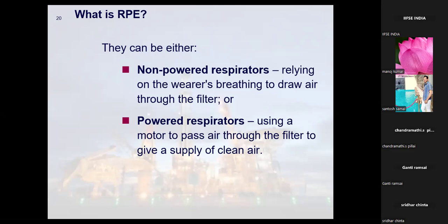See, this we check when you have sandblasting. We definitely check the quality of air that is supplied by the compressor. It can be the sandblasting compressor directly, or it can be a different apparatus. During that, an HSE person observes the quality of the air. This can be through your gas detecting devices.